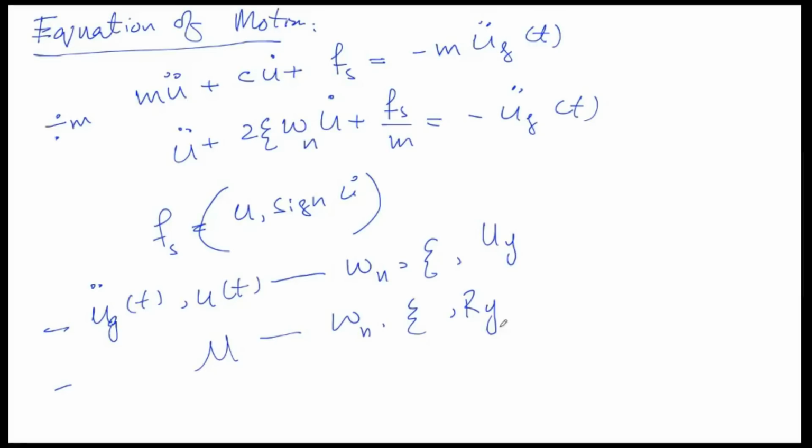And we will see, and it is also shown by past experimental tests, that if you double the ground acceleration, the ductility factor is doubled. And there is also another way. If you use the same ground motion, but reduce the strength reduction factor by 2 times, again you have the same ductility demand. So you can get the same ductility demand either by doubling the ground motion or by reducing the strength reduction factor by half.